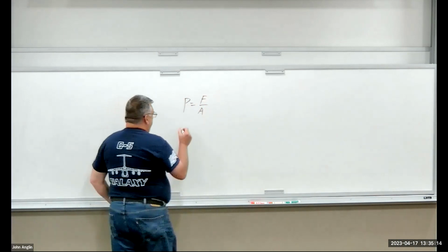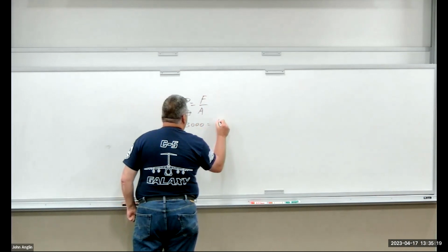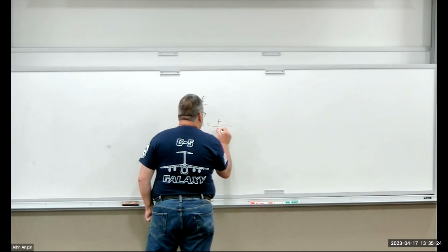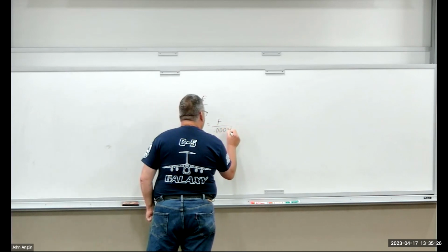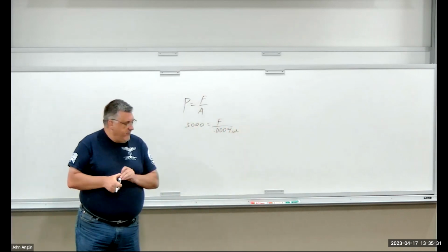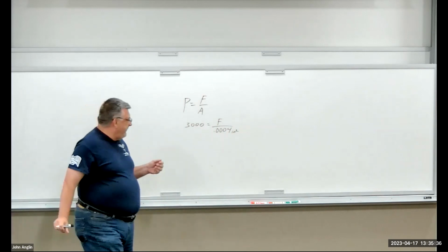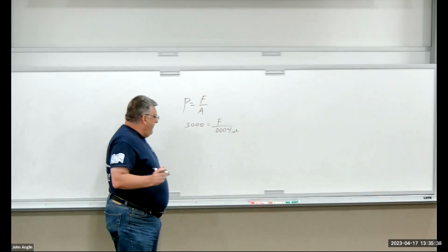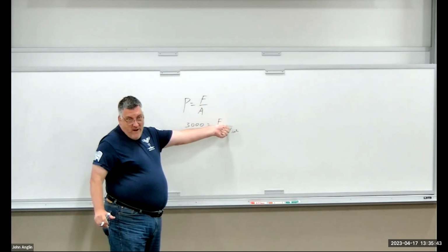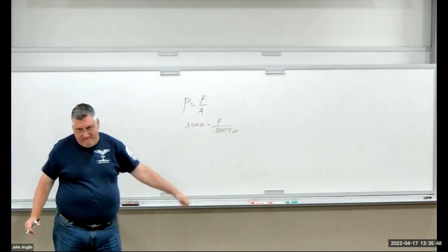Well, if my pressure is 3,000 PSI, and the area of that pinhole is 0.0004 square inches, something very, very small, then look what happens. That force goes way, way high. This is enough to cut your fingers off and you wouldn't even feel it.